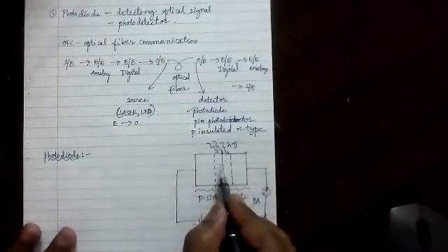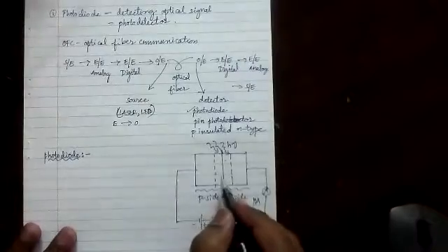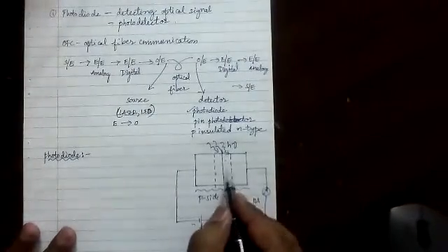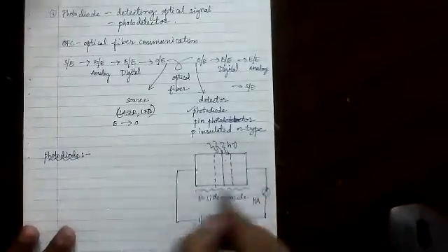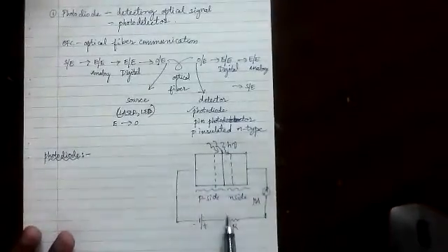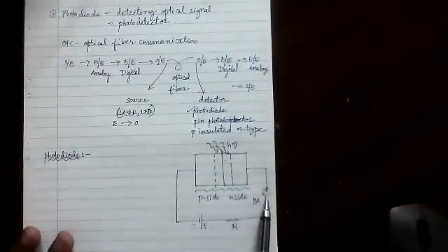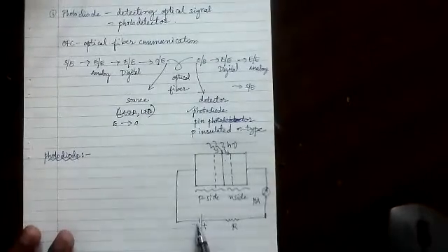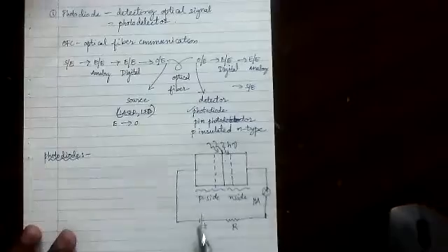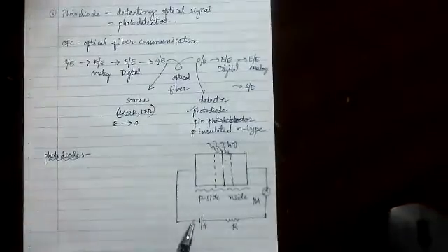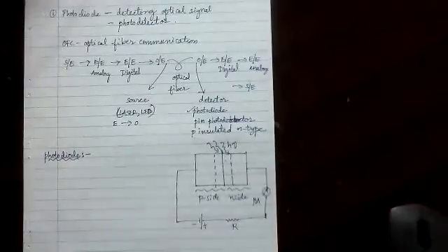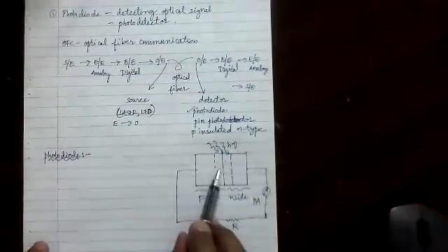It will provide enough energy for electron hole recombination, and when the electrons and holes flow in opposite directions, you can see the flow of current here. Sir, you may ask, already you have applied enough potential. No, that potential is not enough to drive. Suppose we have given only 0.6, it needs 0.7 to flow.